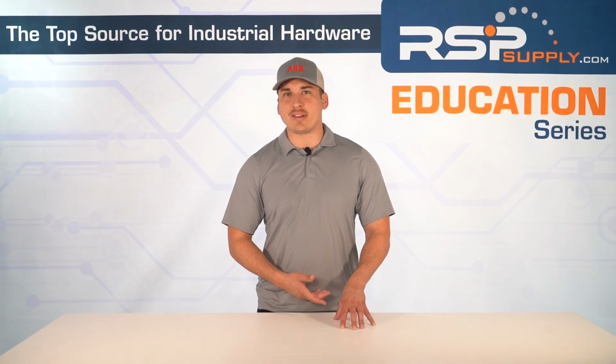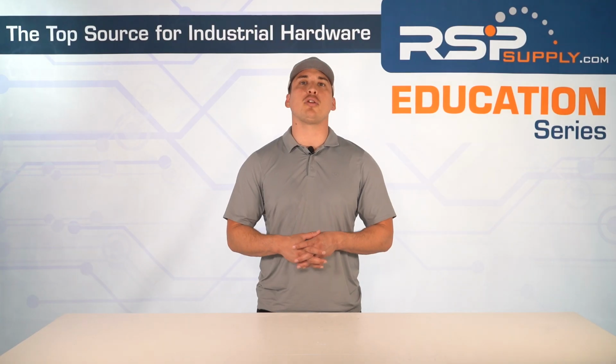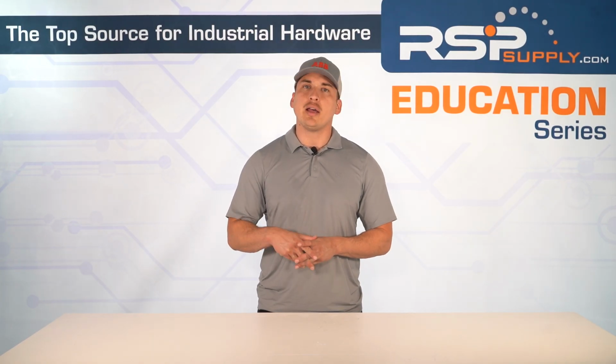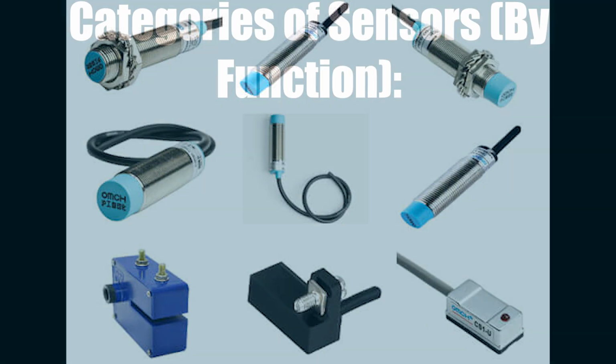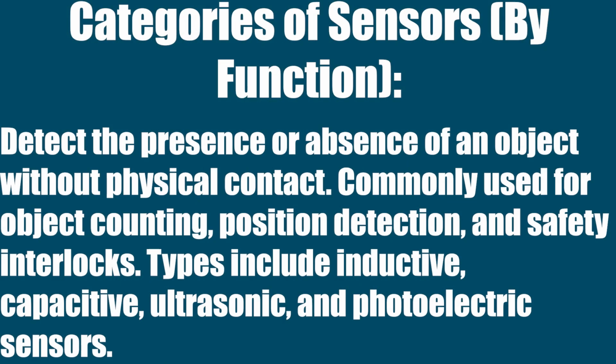Sensors come in many different types. Each one's designed to measure specific physical phenomena. Here are some common categories based on their function. So proximity sensors. These detect the presence or absence of an object without physical contact. They're often used for object counting, position detection, and safety interlocks. Different types of proximity sensors include inductive, capacitive, ultrasonic, and photoelectric sensors.